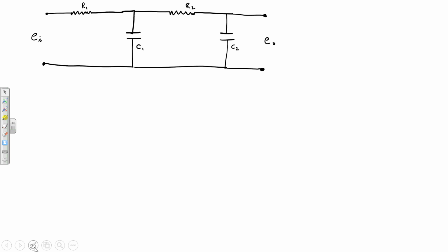And I'm going to assume this current I1, and this current I2 is flowing like that around there. So if I1 is flowing in here, and I2 is flowing there, then what is flowing through here? You can call it I3 if you want to, but can you express it in terms of I2 and I1? I2 minus I1? Or is it I1 minus I2?